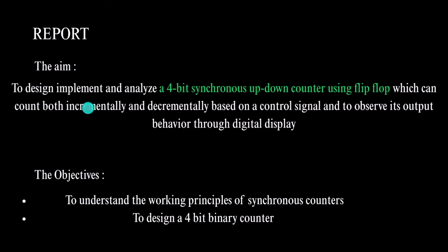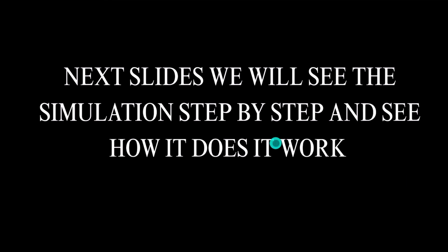The aim of this report is to design, implement, and analyze a 4-bit synchronous up and down counter using flip-flops, which can count both incrementally and decrementally based on a control signal, and to observe its output behavior through a digital display. The objectives: first, to understand the working principles of synchronous counters; second, to design a 4-bit binary counter. In the next slides, we will see the simulation step by step and how it works.